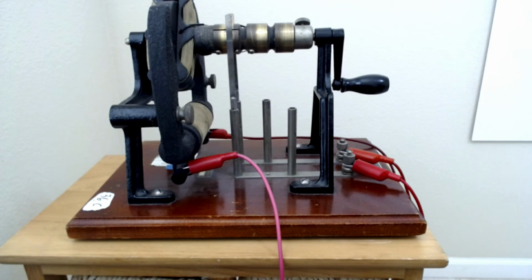Okay. And the thing is if you need more voltage, then you're going to have to buy some more batteries too. We gave you 2 because that's what we want you to run it at. But if you need more, then you're going to have to get some. Now, last semester, some folks tried to use a 9-volt transistor battery. They have a high internal resistance, so it's not going to work. These have a lower internal resistance, so it can actually supply a lot more current.